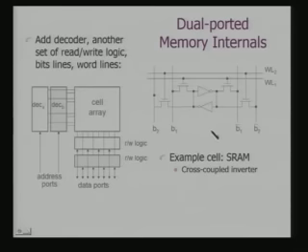So, I now have dual ported read access from SRAM. In fact, dual ported memories are very common in SOCs and on-chip memories for various DSP processors, as well as registers. The register bank implementations are also through this kind of dual ported SRAMs.